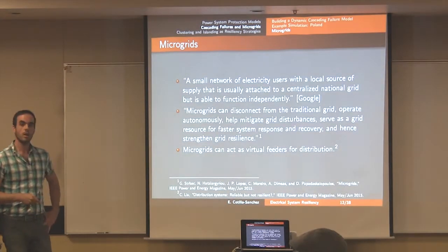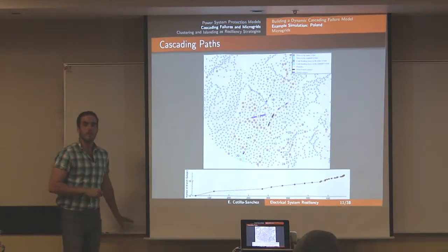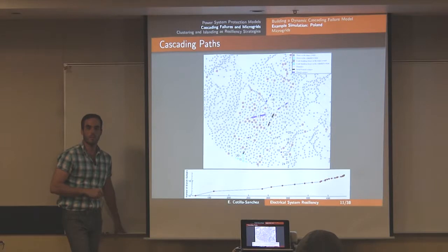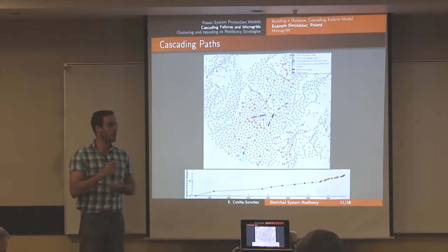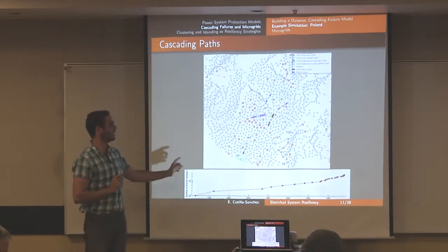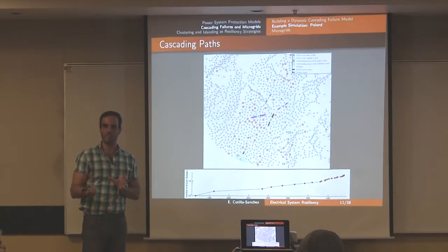Is it possible to predict what substation would blow given that one at the beginning goes? Yeah, so in any kind of cascading simulation, you are not going to get a lot of information just from one cascade. So the type of simulations that we are doing are basically Monte Carlo sampling of many of them, so that you can start understanding where the critical lines actually are that are involved when we have trouble.